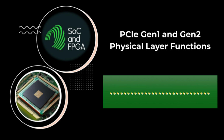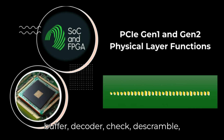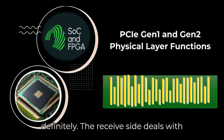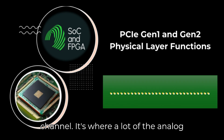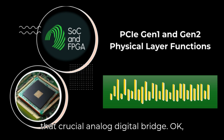So receive is: recover clock and data, deserialize, deskew and buffer, decode and check, descramble, unstripe, send up. Much more involved. Definitely. The receive side deals with all the imperfections of the real-world channel. It's where a lot of the analog and digital magic happens. The PHY is that crucial analog-digital bridge.